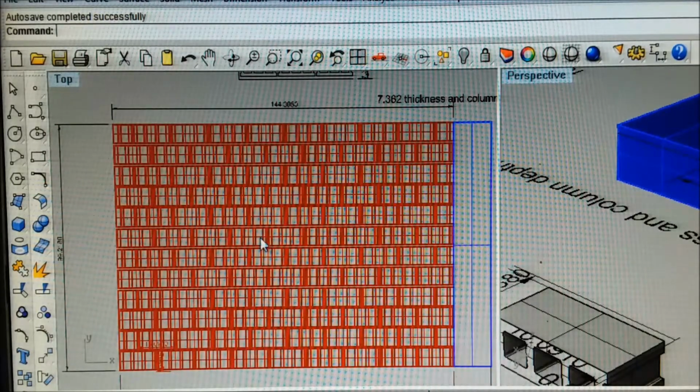The core should actually be filled with a small gravel and sand mix rather than the mortar, but common practice is just to dump extra mortar in it as you go.